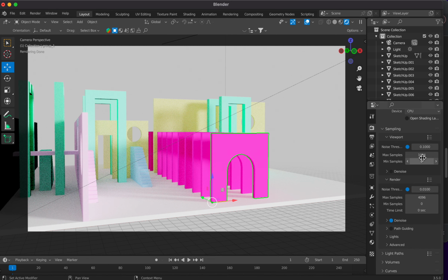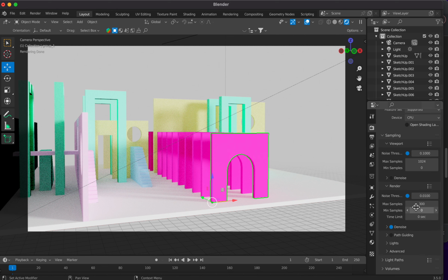We're ready to go. Max samples, we might put that down when we're ready to render. We might start off not too high, depending on how long it takes, as each sample can take a while. So I'd be tempted to do something like 300 samples just for starters to get things going. That's still a fair bit actually. Let's tune that down. 300 is going to look pretty decent, but I'm going to put in 150 just for getting things going.